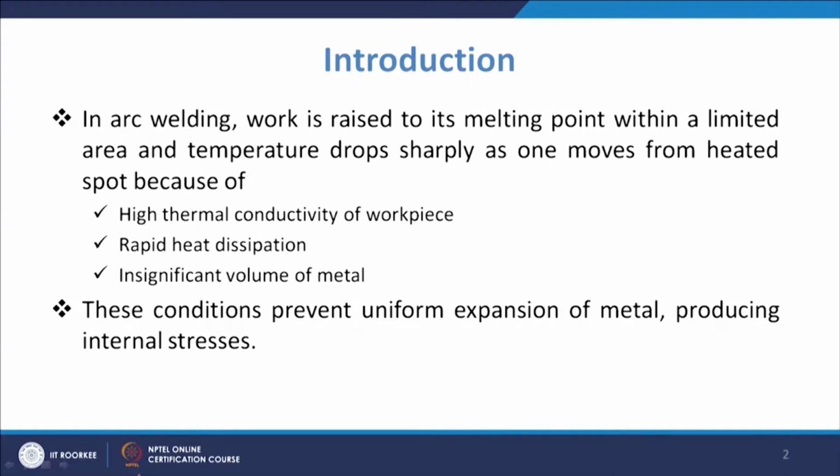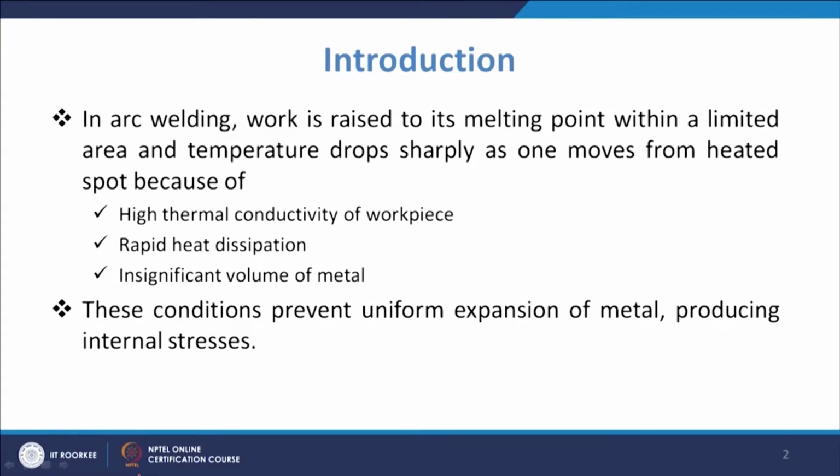First of all, in arc welding the work will be raised to its melting point within a limited area. So, in a very limited area you are increasing the temperature to a large value, and then the temperature will drop sharply as we move from the heated spot. The reason for the sharp decrease of temperature is the high thermal conductivity of the workpiece.